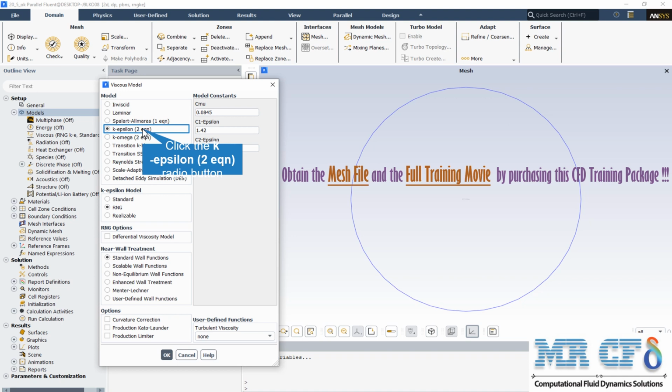The RNG theory provides an analytical formula for turbulent Prandtl number, while the standard K-epsilon model uses user-specified constant values. And while the standard K-epsilon model is a high Reynolds number model, the RNG theory provides an analytically derived differential formula for effective viscosity that accounts for low Reynolds number effect.